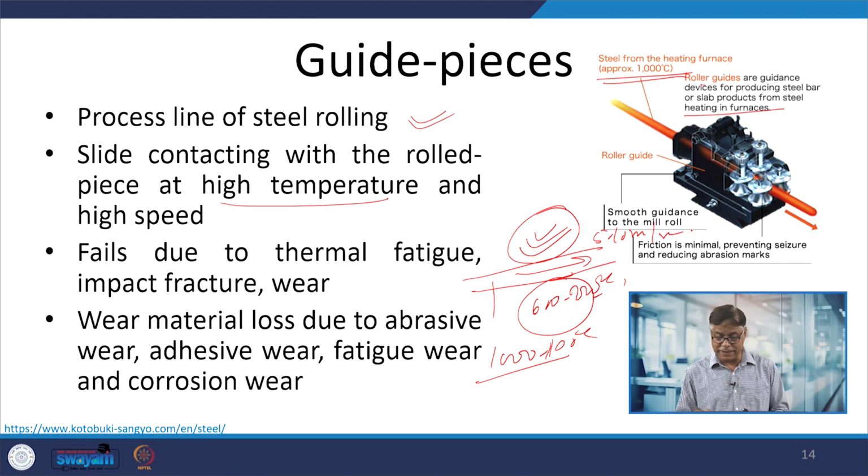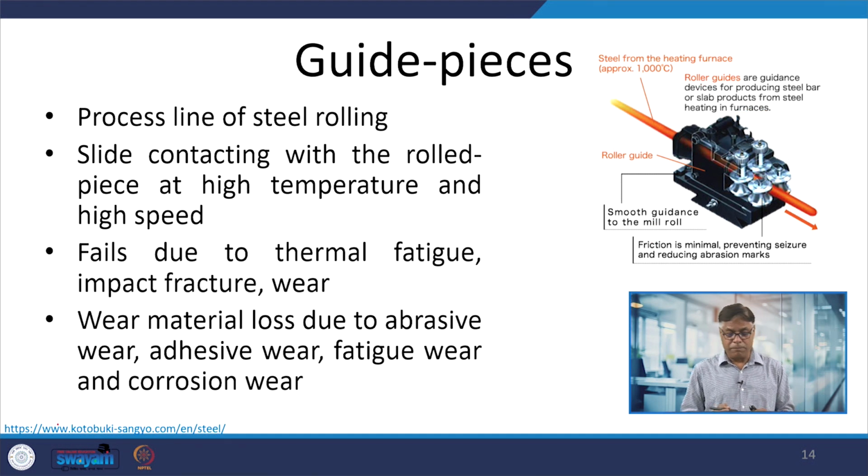If that is the case, these are very severe conditions as far as operation is concerned, and the guide pieces under such severe conditions tend to fail, because there is heat and there is continuous rubbing of the bar. So, this leads to thermal fatigue. This is one, and there is also a continuous wear of the material.